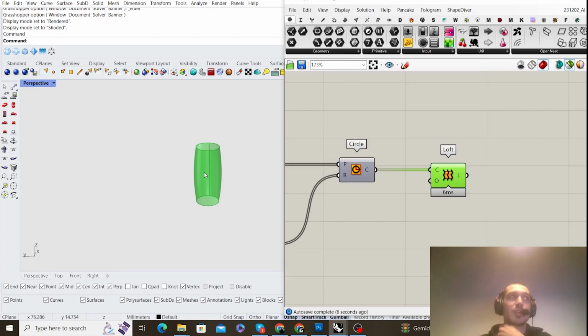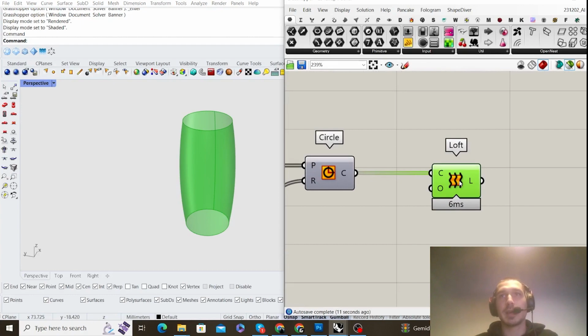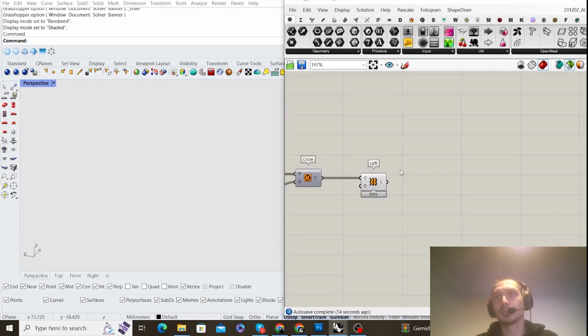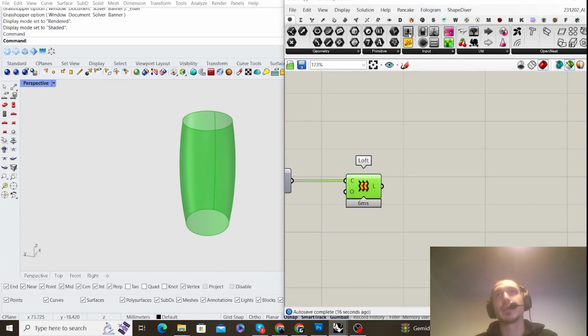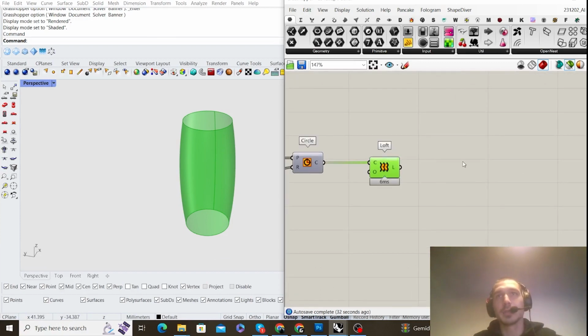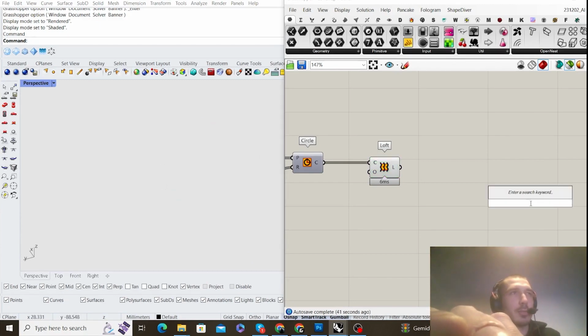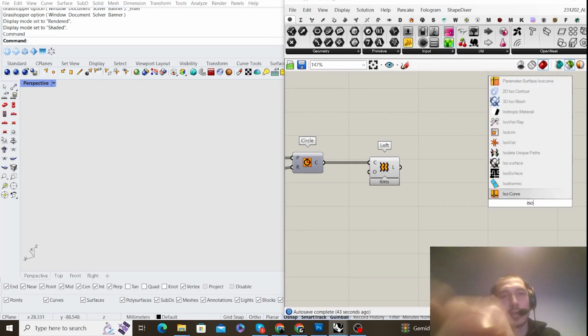So here comes the tricky part, because we need to do the panelization. But if we carefully look at this tower, we should not cover the entire facade. We cover about half of it. In order to cover a part of this facade, let's use the isotrim. We can also use parametric stabilized surface, but let's use isotrim.